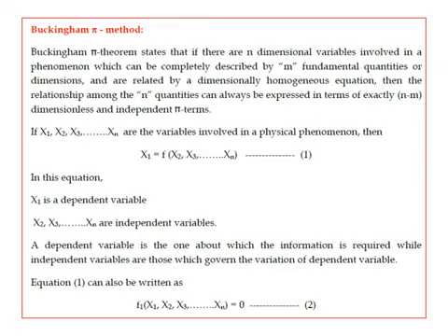That's the reason why the analysis method can be adopted only up to a maximum of 5 unknowns, where you can express 3 unknowns in terms of the other 2 unknowns which are very important. But when the number of unknowns goes on increasing, it is very difficult to solve by the analysis method. Therefore we can go for another method which is known as Buckingham's pi method.